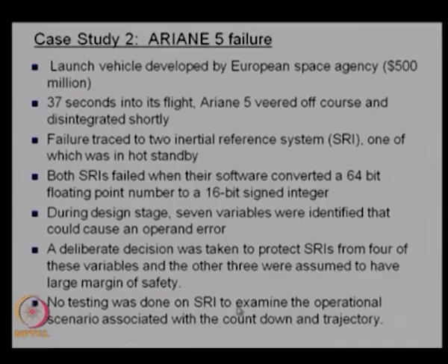So the SRIs are basically used during the initial stage of the flight. So they did not do any acceptance test to see whether this kind of a scenario will be generated or not. Since they have identified 3 variables which can actually cause an operand error, they could have tested these conditions to ensure that this will not cause a problem, but unfortunately one of these variables resulted into an operand error, and the whole launch vehicle was destroyed by that simple